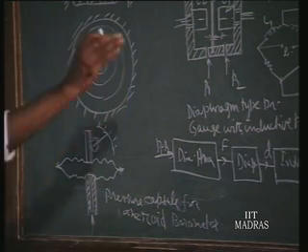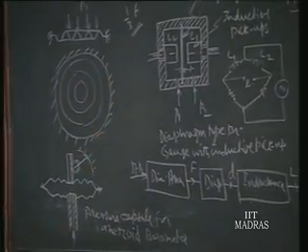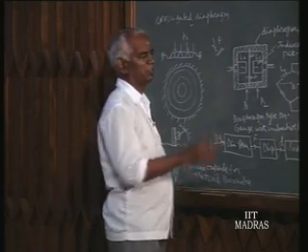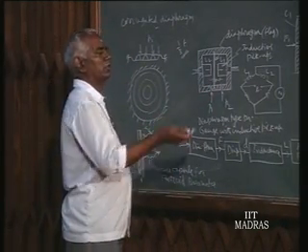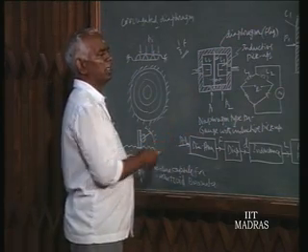We have seen how the flat diaphragm deforms, and the deformation is picked up by strain gauges. That is one possibility of sensing the deformation of the flat diaphragm into an electrical signal by using resistance. Strain gauge is basically resistance. So we can use the other principles also.